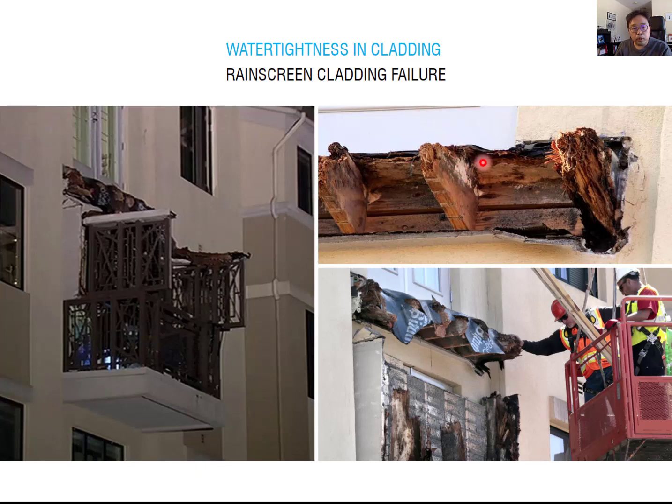So you remember the RAINSCREEN system. Of course, this is a little different from the RAINSCREEN system, but you always have to be concerned about ventilating the air to dry out the water as much as possible. In this case, everything is very tightly capturing water in the space, and the moisture keeps affecting the structure, so the structural member gets weaker. Then 6 people stood on it, and the balcony simply collapsed and failed.